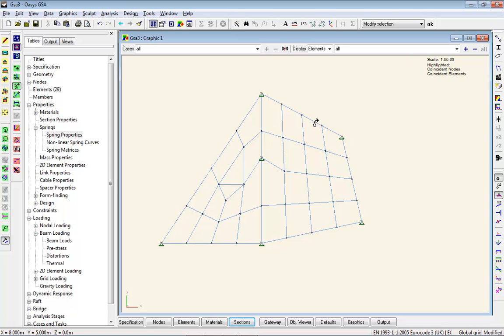We can also do other adjustments on this mesh. We can use the split commands, but with a 2D mesh like a flat slab, you want quite large elements in the middle where not much is changing. So you've got general moment but not much detail, but around the support points the moment's changing quickly, so you need a finer mesh to catch the detail.